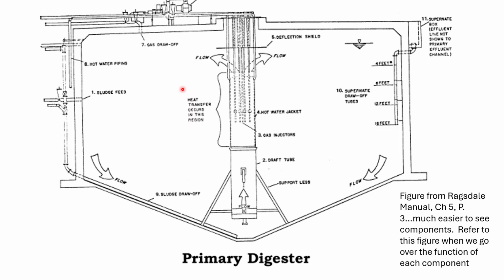So what's happening here is we have at different levels of the digester, we have supernatant, or that separated water. We're just going to start collecting it here, and it's eventually going to go to like a launderer or an effluent, okay? An effluent launderer, and we're going to collect that away, but we're collecting this separated water at different levels of the digester, okay?